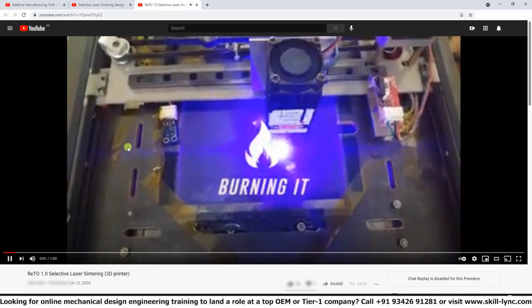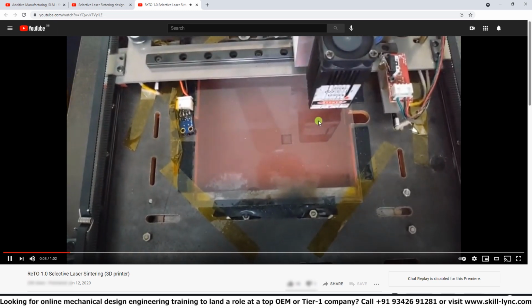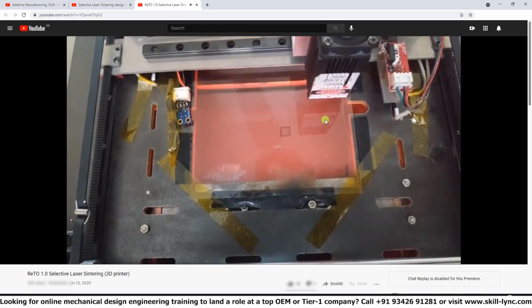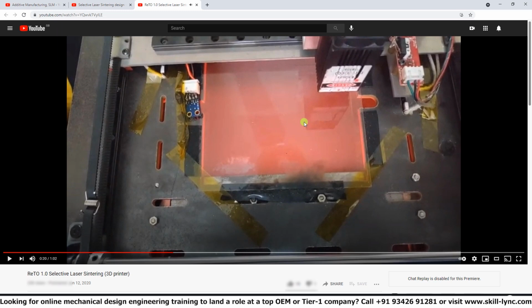Okay, so you can see what's happening right now is a layer of metal powder has been melted. You can see the cross section, they've created a little square on there. And now you can see it's moved down. It's changed color because of the motion of the build platform. It's moving down. And now the roller underneath is depositing a new layer of powder. You can see the cross-sectional area that's been melted over here has sort of disappeared because there's a new layer of powder on top.